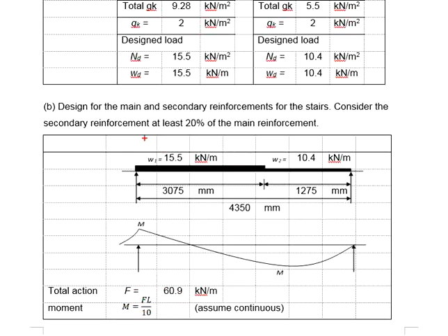So you will need to get the total vertical force acting along the staircase span, multiply by L and divide by 10, and you get the moment. As for the shear load, you will use the principles of static equilibrium to find the reactions supporting the staircase. The reaction shall be considered as the shear load acting on the staircase.